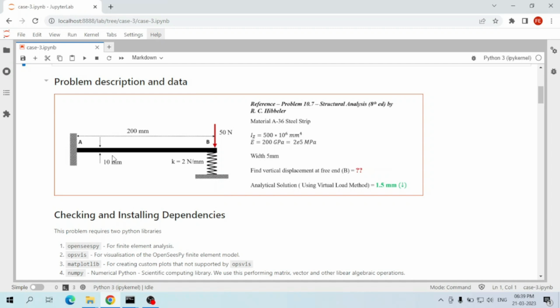Similarly, in roller support, only vertical displacement is restrained and all other translation and rotation DOFs are allowed. Hence, we put 0 only for the vertical translation DOF and let the member move or rotate in other DOFs.